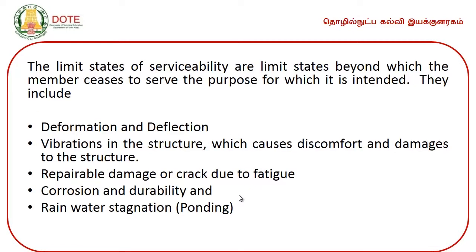And the other, serviceability condition or limit state of serviceability, includes deformation and deflection, vibration in the structure, repairable damages, corrosion and durability, rainwater stagnation or ponding. This will happen in the sloping roof, probably in the asbestos steel roof trusses at the gutter portion.